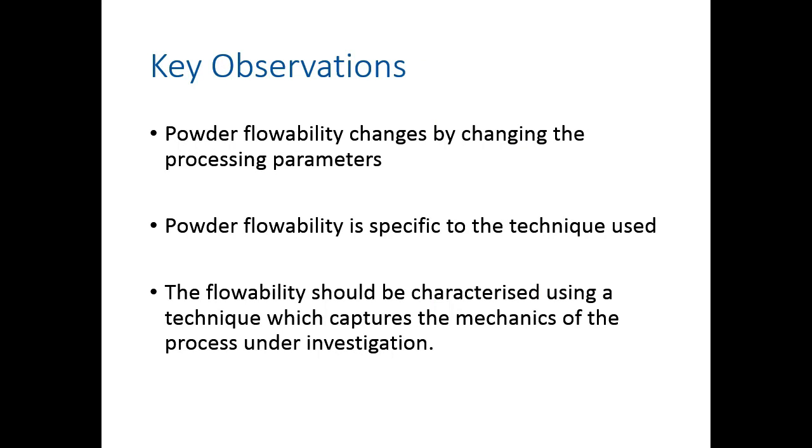Just to summarize the key observations that we had, the powder flowability changes by changing the processing parameters. It is specific to the technique used, and it should be characterized using a technique which captures the mechanics of the process under investigation.